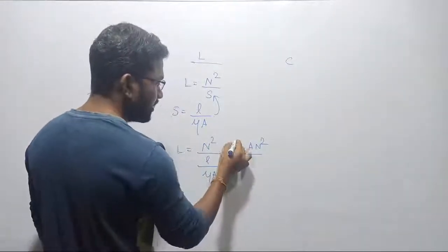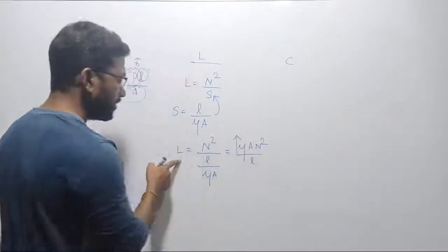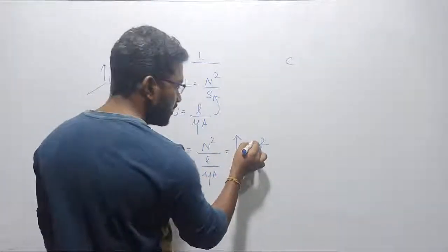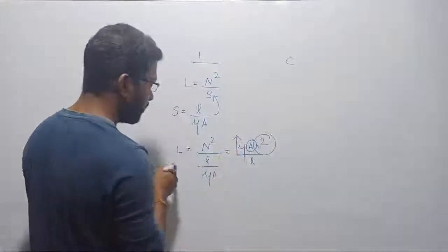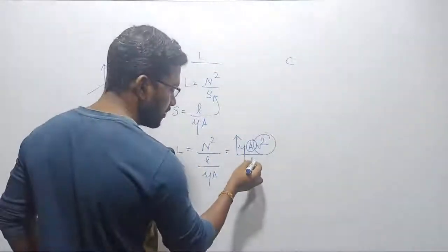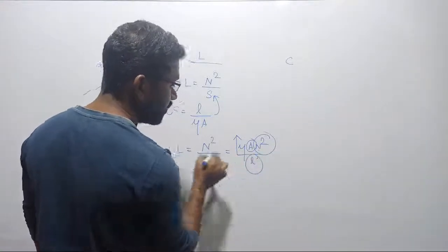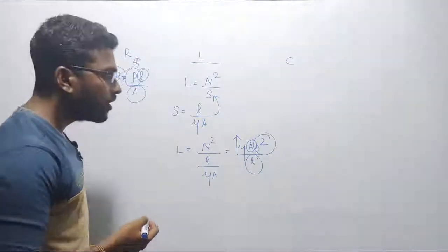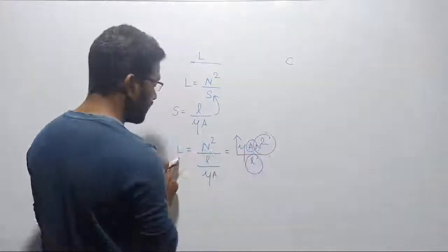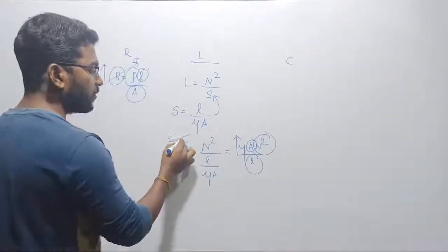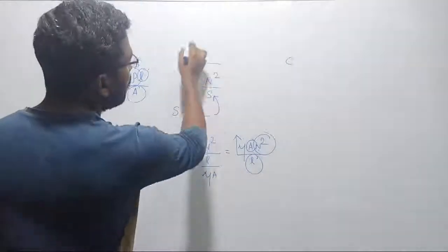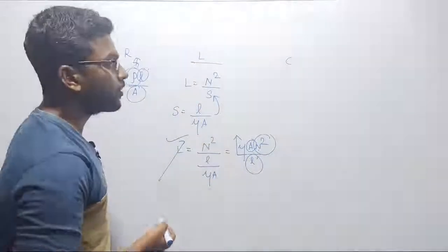By changing the permeability of the material we can change the inductance, or by changing the area, or by changing the number of turns. This is the number of turns, this is the length of the wire; both are not the same. By changing the length of the material we can also change the inductance. That is how we produce variable inductance in a passive inductive transducer.